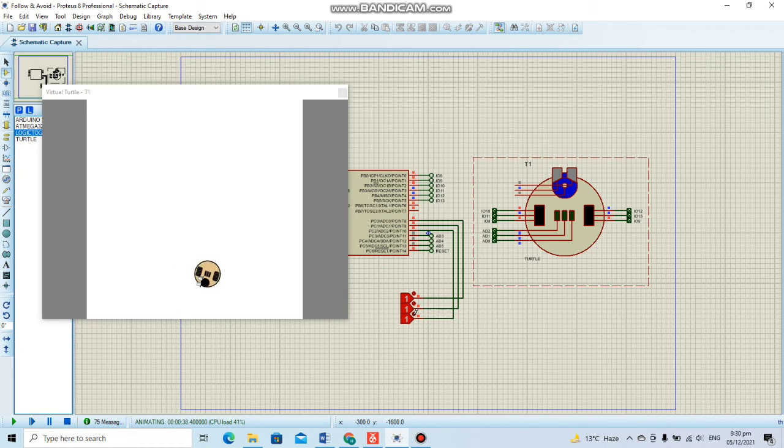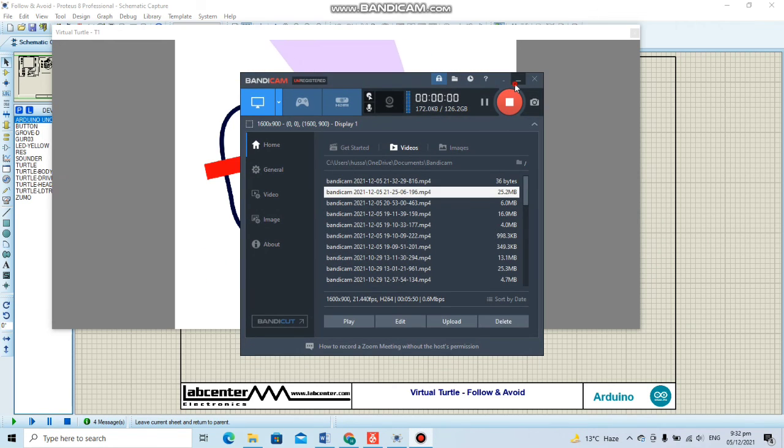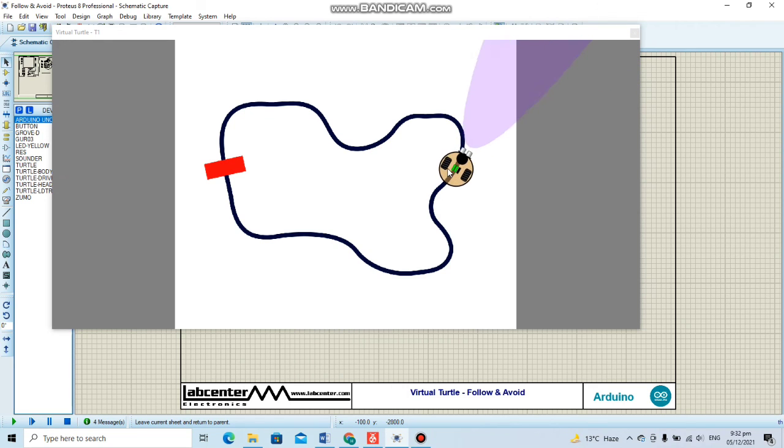as the right priority is set, when all of them are 1, again we can see that it's turning towards the right. So now let's test it. I will test it on a road or a map with a line and see what happens. Now here I have put the robot onto the map and the line, and we can see that it is following the line according to our logic. It's a bit shaky, but it is following the line.